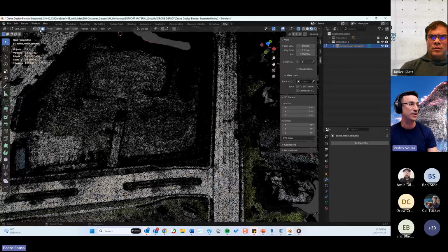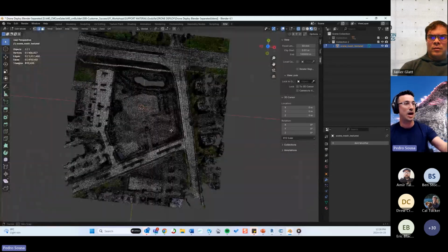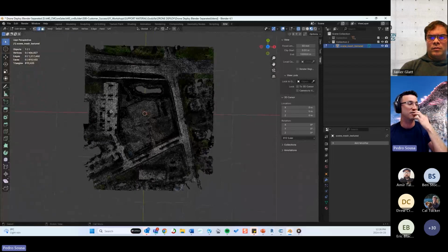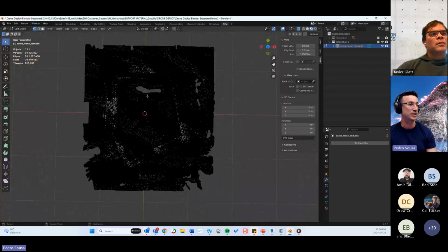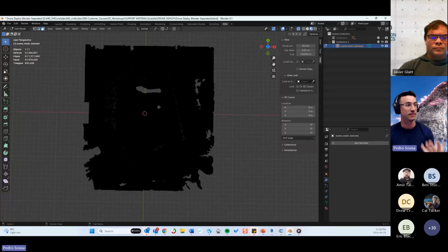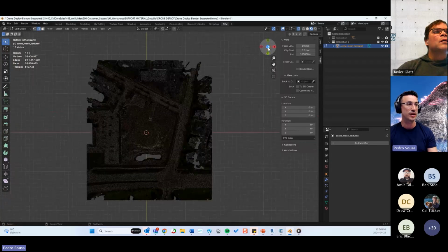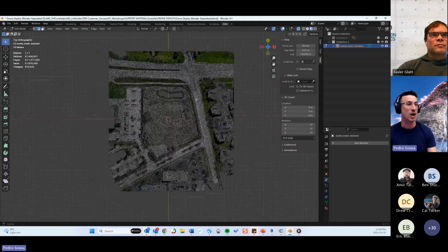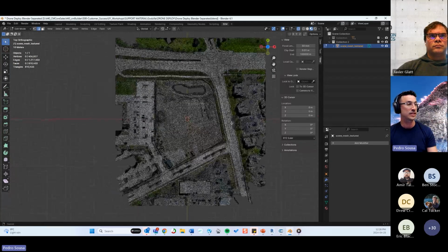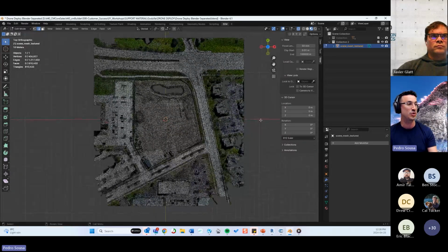I prefer to keep edges because from a zoomed out perspective, the edges will give me a better view. If I change this to vertices, it's harder for me to see exactly what that geometry is. Faces is even worse. And you can also use some tools over here to snap your view from the Z option and so on. The simplest way to do this is to do a lasso selection on specific parts to remove those parts from our main surface.